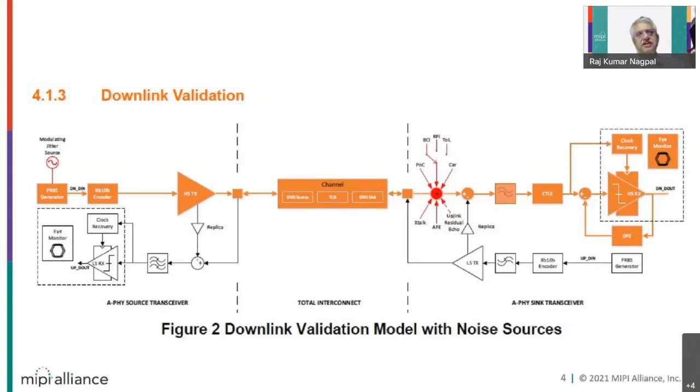It has got HPF and LPF components, so you tune it in a way that you are maximally rejecting the noise environment and accepting the signal spectrum. So this is a band pass filter. Then you have got CTLE, and then you have got a DFE. By the way, this is profile one, and modulation is NRZ, and this is a very basic building block.